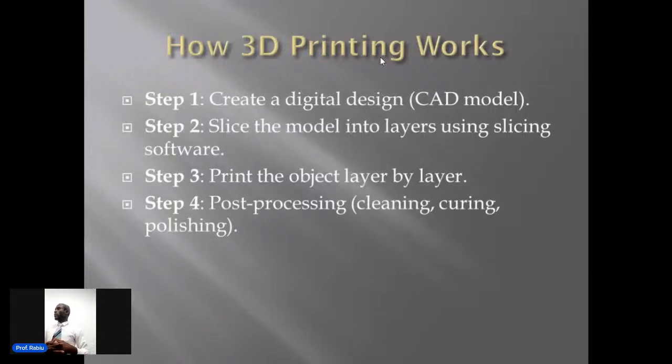After creating the model, you need to slice the model, right? The idea is to make sure you give a sequence in uninterrupted manner so that we can have a successful printing of an object without any issue. What happened during that slicing? It tells you if your model has an issue, and it will identify those areas that has issue.